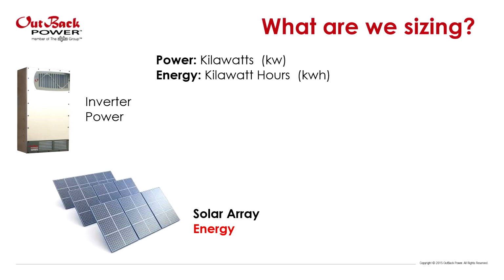Next is the solar array. This is sized based on energy. It's based on energy consumed in one day by the loads, and this includes day and night loads. So the solar array is sized by energy.